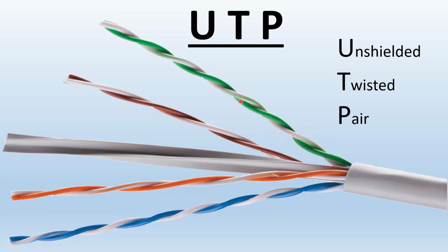So if the magnetic field is scattered around because of the twist, not straight cable, it's a twisted pair, then the magnetic field will not have the consistency and enough power to bleed itself onto the other pair. And if the other pairs are twisted at different rate, then there's even less of a chance of signal bleeding through or creating a crosstalk between the pairs.